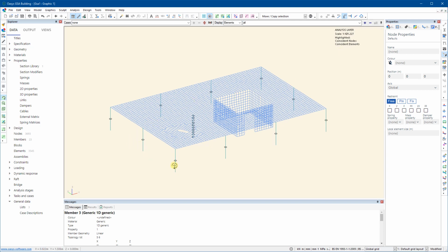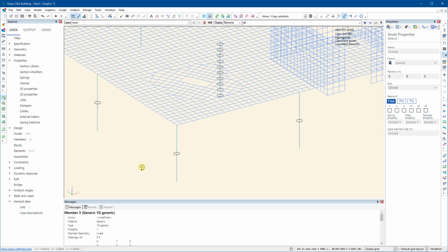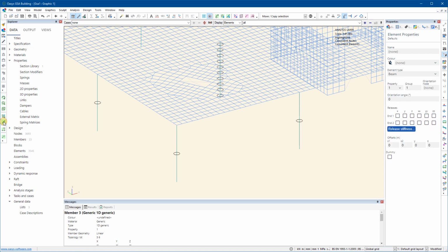And now the thing that you see is that the elements that we've got for the column show the circular section. So if we go to the left, if we choose the member selection tool, if I click on that, you can see it's telling me that that column is property 1. And property 1, as we know, we've just entered it, is a 300 diameter column. If I go to the drop down now, you can actually see property 1's got the column name on it. So again, it makes it quite easy to assign things.